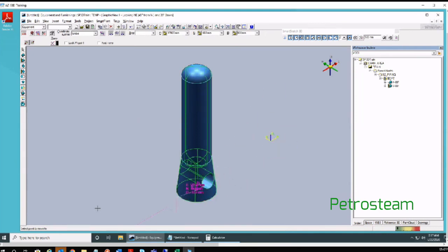Assume that it was outside somewhere here. By mistake, you defined your equipment definition here and then built your shapes here. To bring it within, if you know the shapes' coordinate, you can input the values over here after you select the move command, and then move it within the graphics you have built. I will right click to come out of the command. For my equipment, the reference position is fine now. But if there is any problem, please move it as per your requirement.